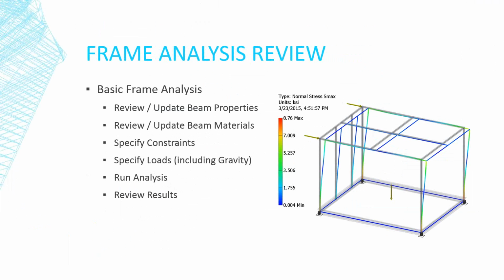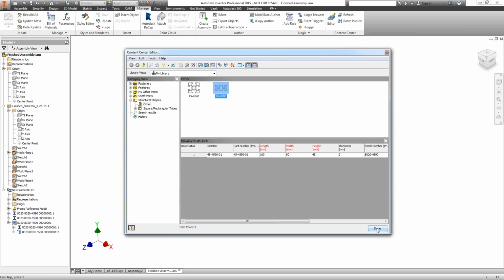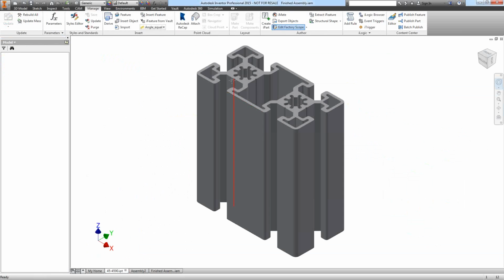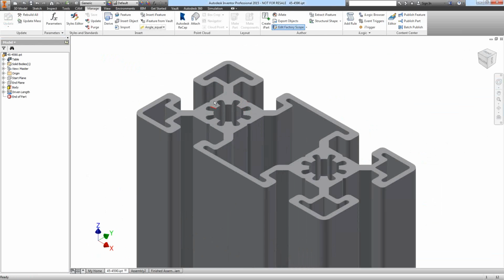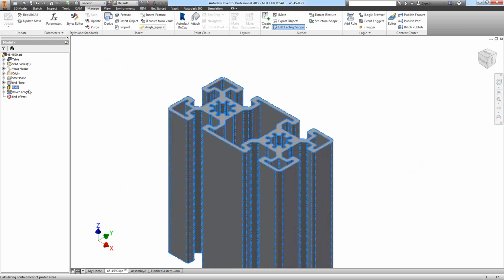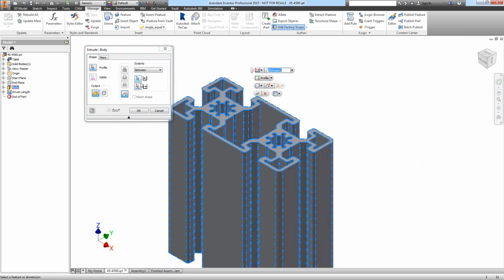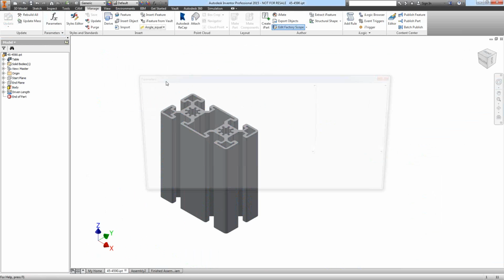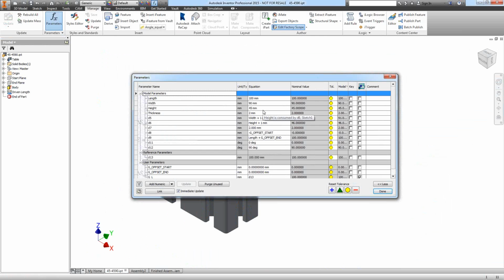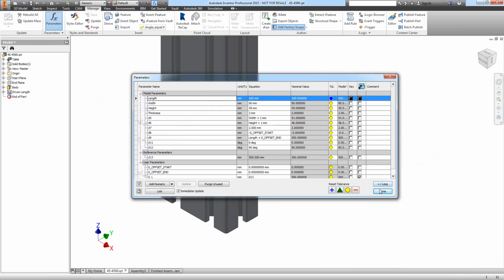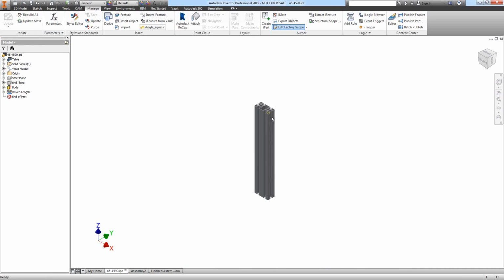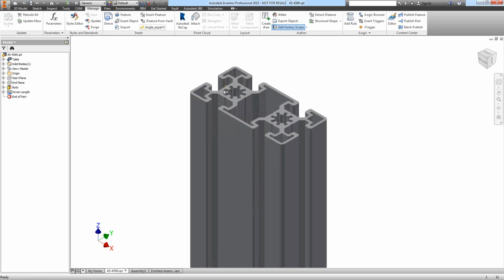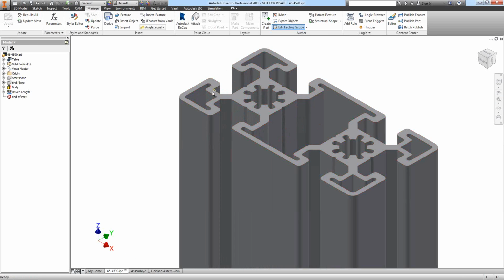The thing is, if you use something like frame analysis, it's much, much faster than a traditional analysis. Because if I'm going to do a traditional FEA analysis on this part and it's very long, let's say it's, what are we looking at? Where's the length here? 500 millimeters long. If I'm going to mesh this with a traditional FEA analysis, the elements are going to have to be really tiny to do a good analysis on this.